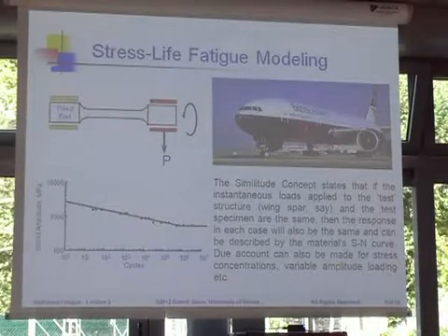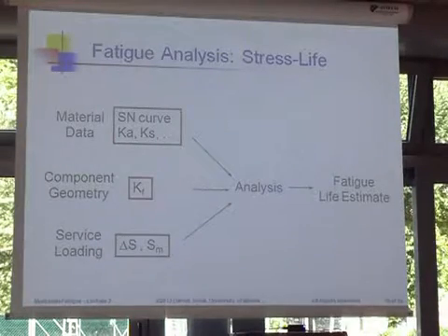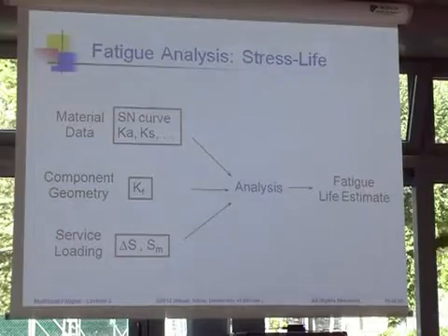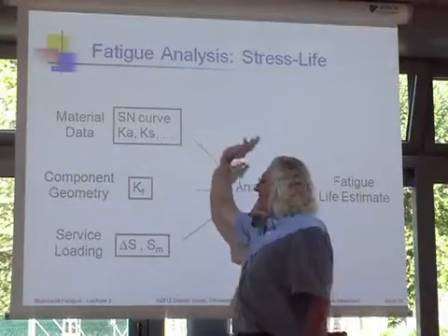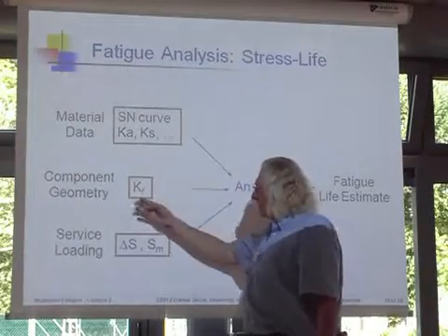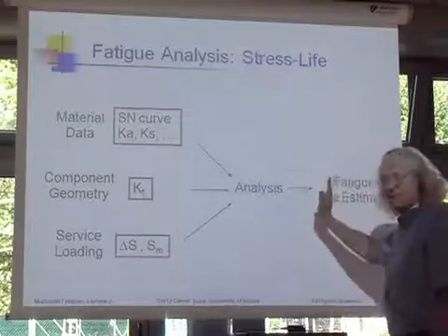So that's stress life modeling. Let's look at it a little bit. So it's easy to do the analysis, right? You choose some things about the material's S-N curve, and then we have some modifications for surface finish and so on. And we know about stress concentrations, and we know about loading, and everything works.